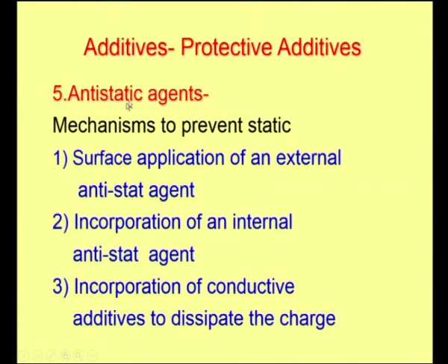Now, the anti-static agents are added to prevent this buildup of static charges. These are the mechanisms to prevent static charges. One way is surface application of an external anti-static agent on the product, or incorporation of an internal anti-static agent which will help the material prevent the internal building up of the charges.